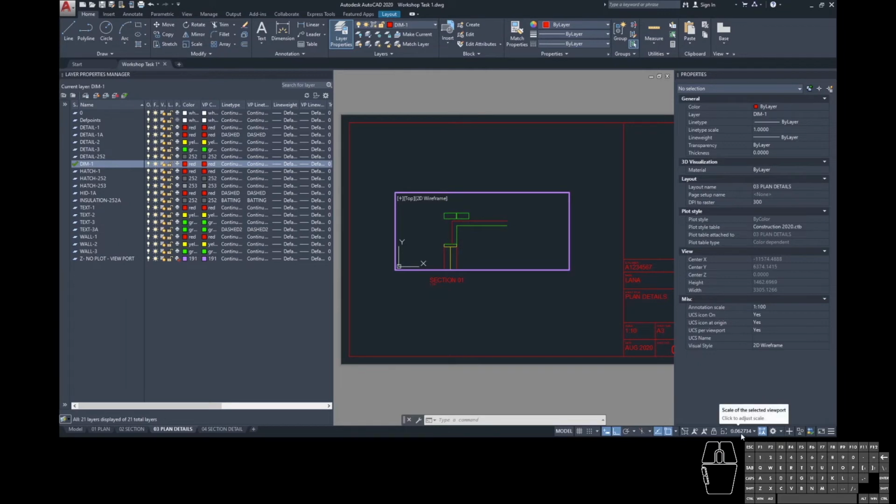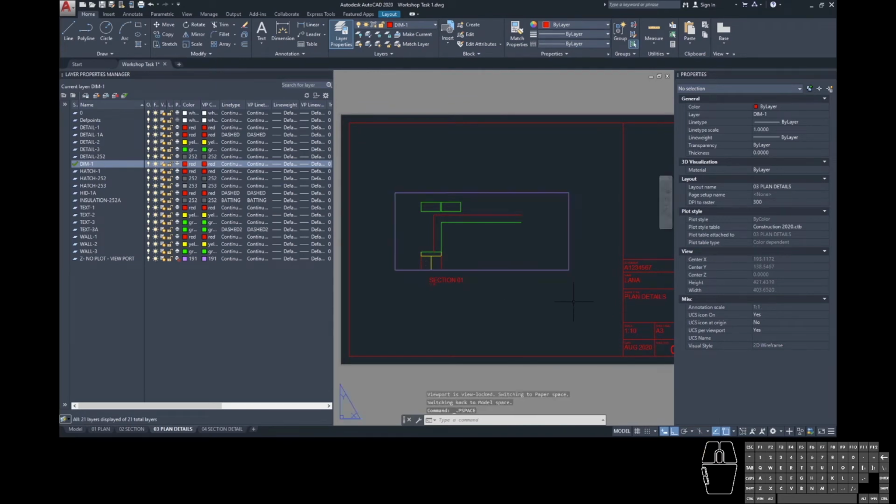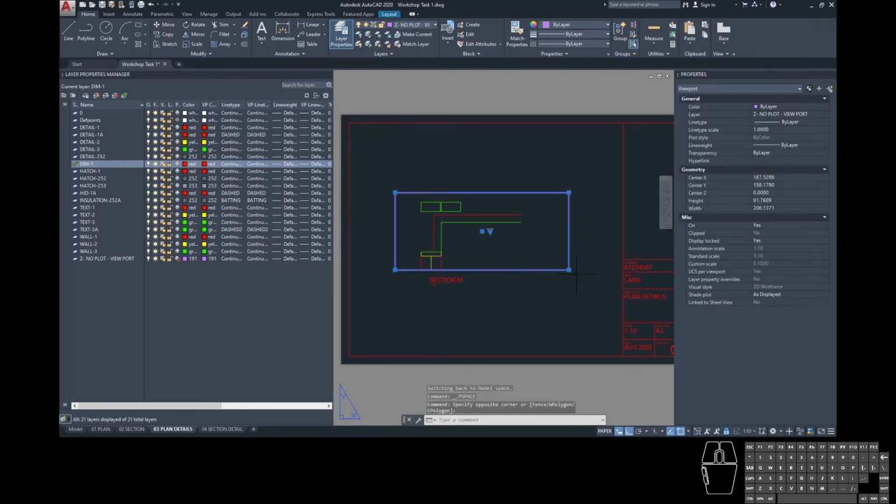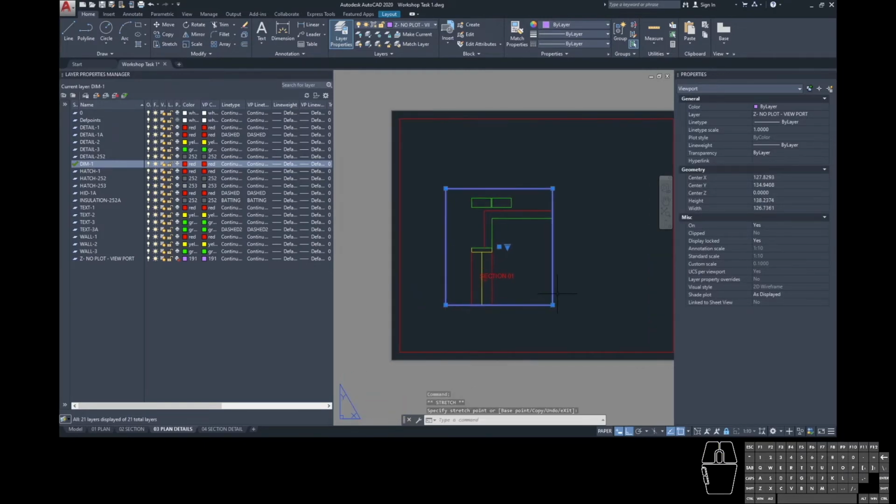And then obviously we need to make sure that we are putting a scale on this. So while this is showing a decimal point at the moment, we actually want to use the scale. We want to specify 1:10. It's immediately going to scale to 1:10. We're going to lock it again, so we're not going to accidentally scroll and undo that. I'm going to double click to deactivate my viewport. And then I'm just going to use the control points to drag this around, just get that to sit where I want it to sit.